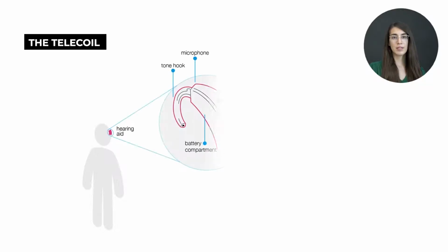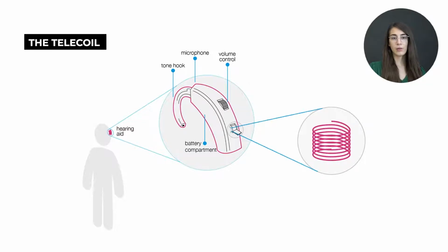We drew inspiration from sensory augmentation, focusing on people with cochlear implants or hearing aids, by visualizing, emphasizing, and complementing their ability to pick electromagnetic signals through their device. The T setting, which stands for telecoil, is a built-in feature of most cochlear implants and hearing aids. This T switch turns off the microphone and activates the tiny iron core coil inductor that functions as an antenna. In short, it picks up electromagnetic field signals and converts them into sound.